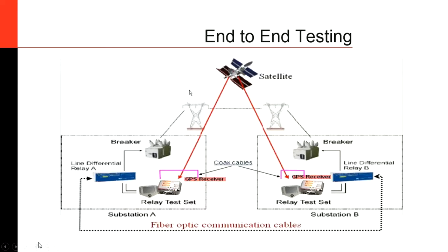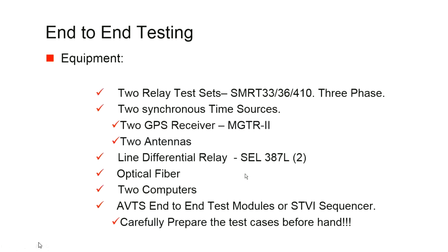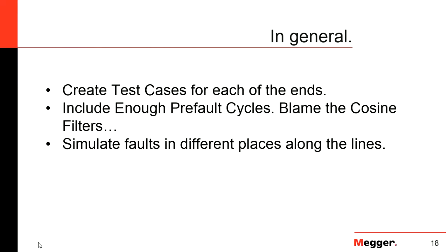Now, when the power system talks about synchronization, what it says is that the frequency of the system is the same in all places of the system. But it doesn't mean that the power system has a common time source or anything of the kind that I can use to actually know when to begin the test at one end of the line or to begin the test at the other end of the line. This is what I mean when I talk about synchronization. I don't know if that's enough as an answer or if I should talk a little bit more.